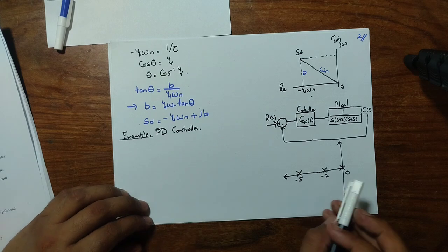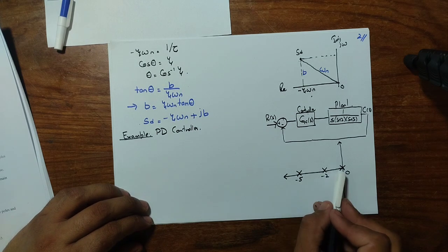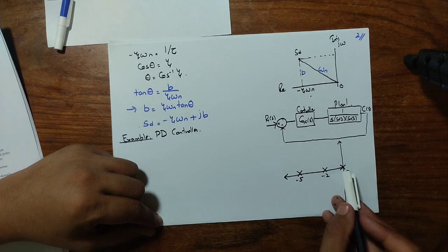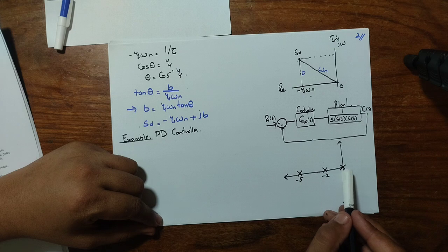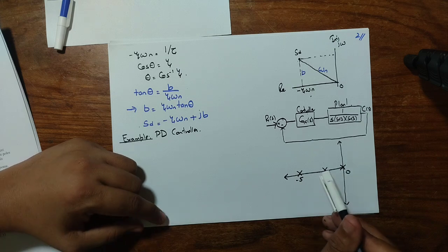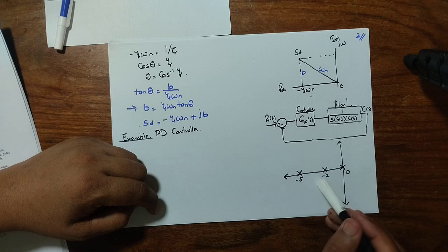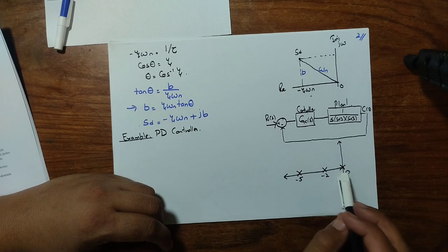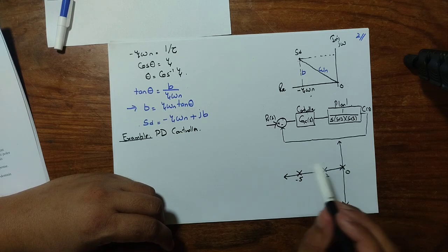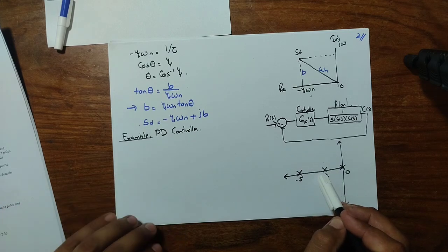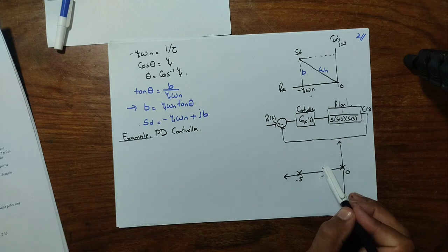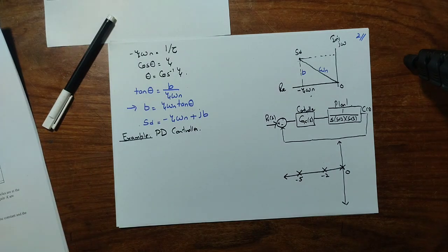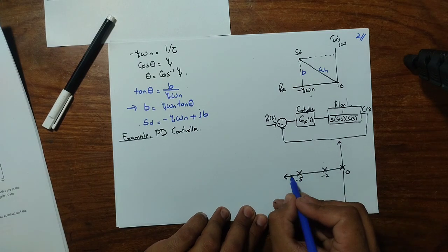These poles are the open loop poles, which means we are not talking about the closed loop configuration, or we can say that for these poles the gain is equal to 0. So we are not operating any kind of control activity in this configuration. The key thing in this example is that we have been asked to first sketch the root locus for this system using just the proportional gain, and search for the critical point. By virtue of just a MATLAB command, I can sketch this root locus, and it comes out like this.